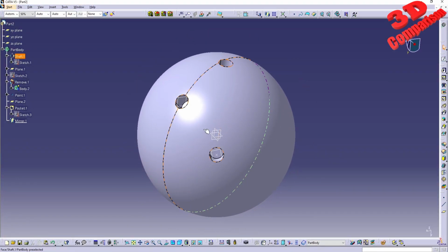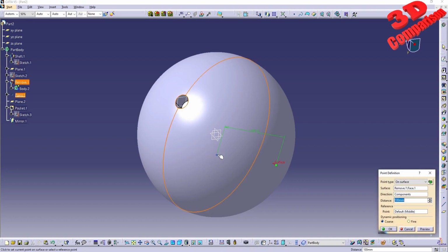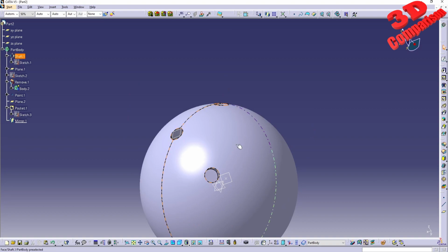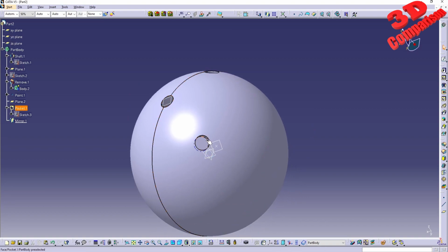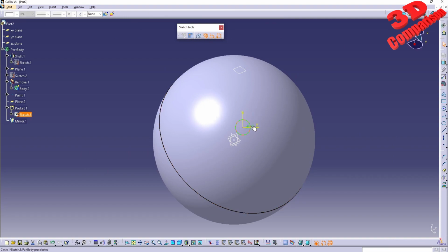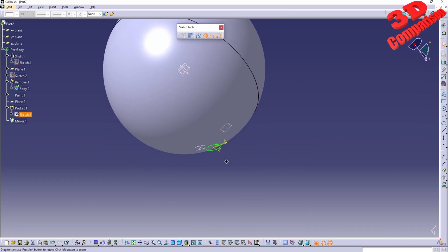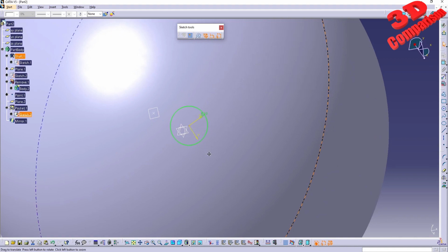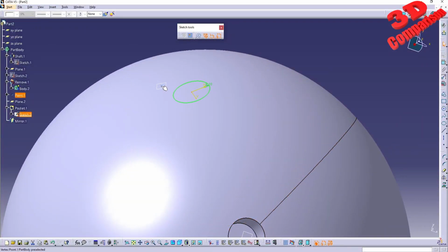If you want to further change the position of the point, you can easily do that. For example, if I will make this all the way to the back, like 80, we're gonna see that the cut will be positioned over here for the pocket. So even though I change that position, this is because we don't have that coincidence between those two properly defined over here. So let's see, this is the point, this will be the circle. I see that the circle is now fully defined, therefore I will have that deleted.